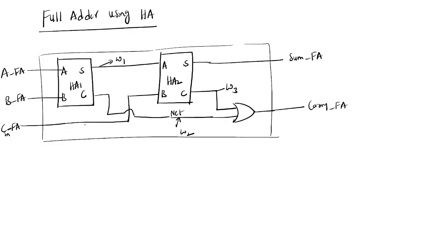We need to write code for the half adder. Okay, so I'm writing the code for half adder. Module half_adder, input A, B, and output S, C.